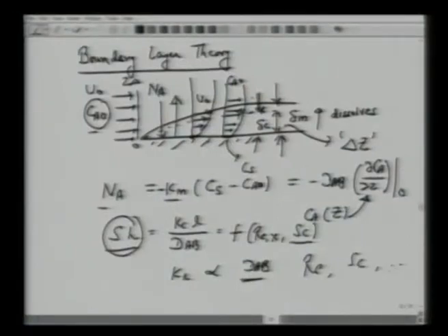So the idea is that, whenever you are solving real problems in mass transfer, whether it's flow in a packed bed, or mass transfer over a flat plate, or you have the interface of gas and liquid, you're supposed to go through the table of Perry's handbook and get the correct correlations, calculate Reynolds number, calculate Schmidt number, or any other restriction which is given, to ensure that you are using the correct expressions for Sherwood number to calculate these mass transfer coefficients. All right.